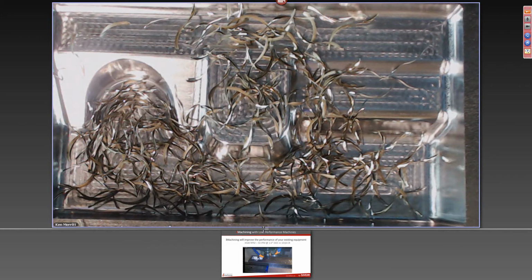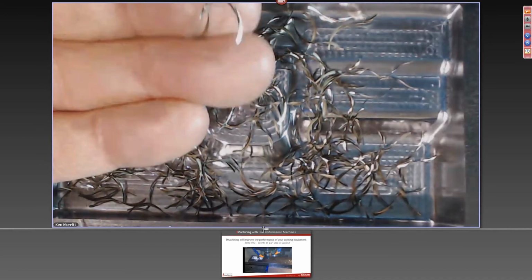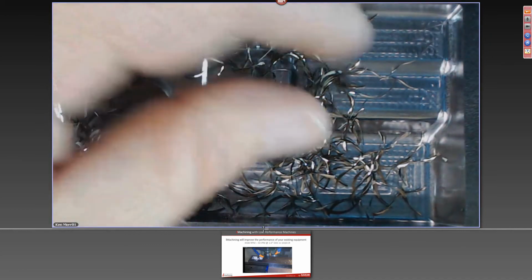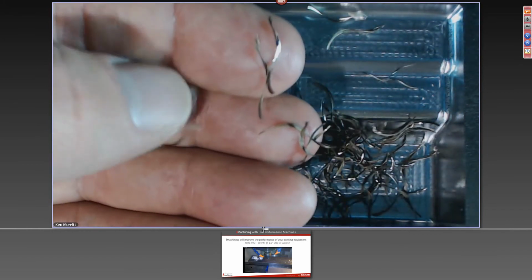And so as the morphing spiral runs and the chip runs between the minimum and the maximum angle, what we do is the programmed chip thickness is for the maximum angle. So as the cutting angle goes down towards the minimum, we increase the feed rate so that we keep the chip thickness the same at that cutting angle. And so you'll see in the toolpath the feed rates going up and down, up and down, up and down all the time when the spiral morph is doing, or even the parallel passes are doing, the minimum to maximum angle ranging. And what that does for us, if you'll notice, these chips are just extremely consistent. No matter where you grab them from in the cut, they're going to be very, very similar in thickness.